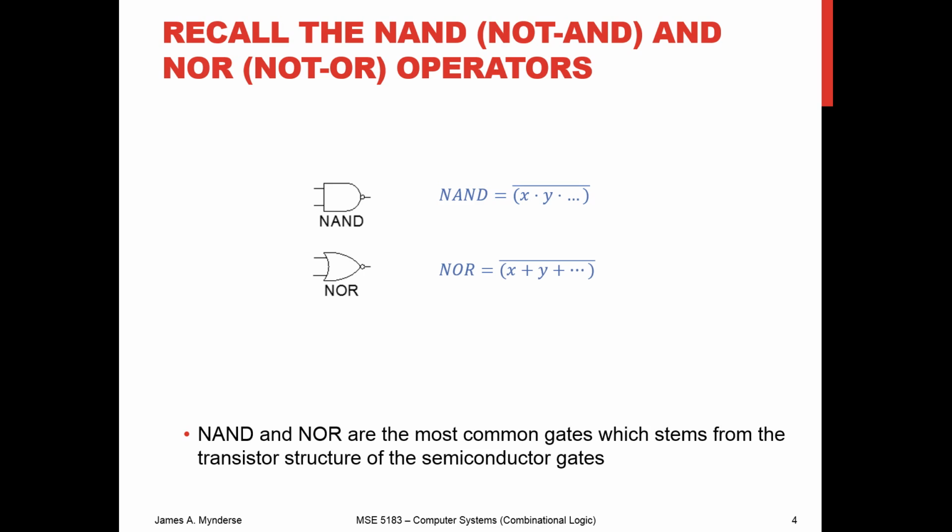And so when we actually put together an integrated circuit, which we're not going to deal with in terms of building an integrated circuit in this class, we want to assemble collections of integrated circuits. But if we were going to design an integrated circuit, we would be focusing more on the NAND and the NOR, because remember, they're going to be lower part counts. They're going to be cheaper and easier to implement at the IC level based on the transistor structure.